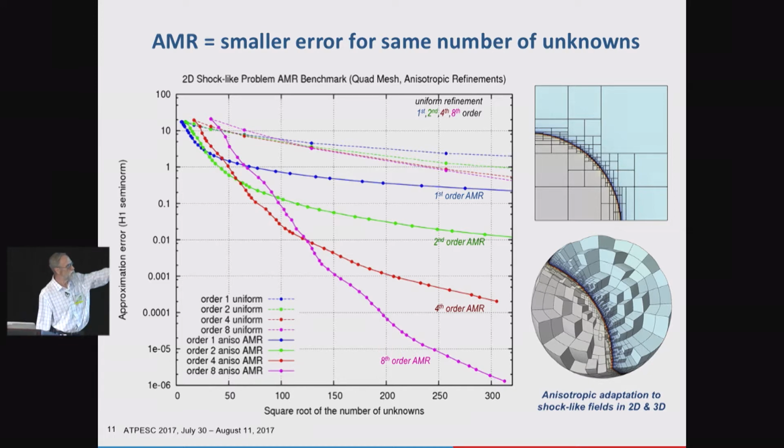So in these particular methods, as was said, you can refine and de-refine, but you can't de-refine past the initial mesh. Whereas in the conforming mesh methods, because they're totally based on the same technologies used in fully automatic mesh generation, you can coarsen as much as you want.